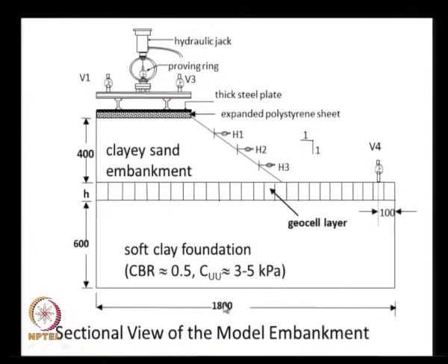The length of this tank is 1.8 meters, and it is filled with soft clay soil almost at liquid limit consistency, which has a CBR of 0.5, and the undrained cohesive strength that we get from the vane shear test is about 3 to 5 kilopascals, very low strength. The consistency is such that if a person stands on this clay, they just simply sink up to the knees.